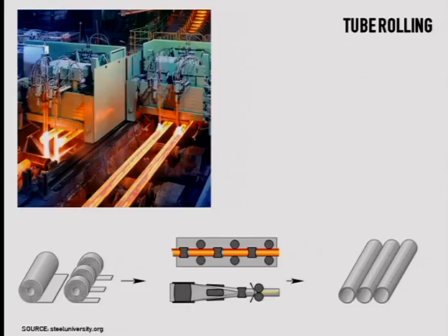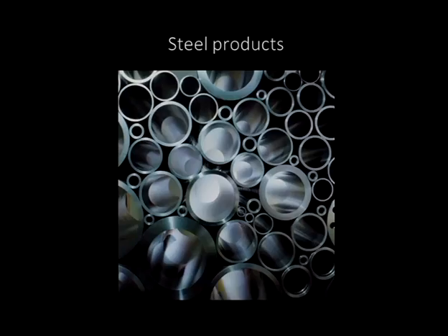We'll see later there is also another way to cold form steel. So you see here the curve, it bends, and then when the 2 extremities touch, there is welding, so that we get this profile. That's also very helpful to reduce the overall self-weight of the material, but still preserving high strength capabilities.